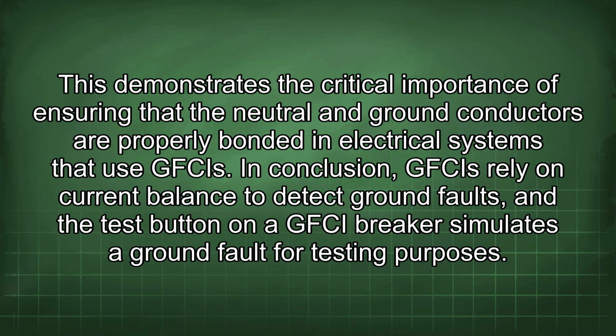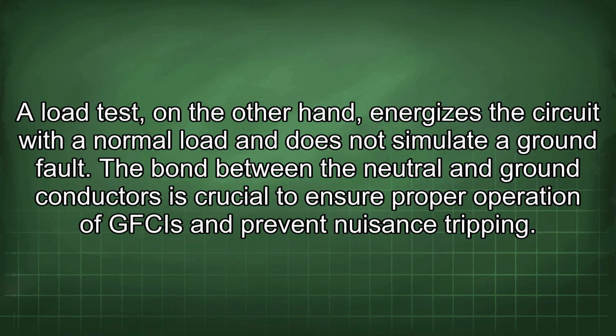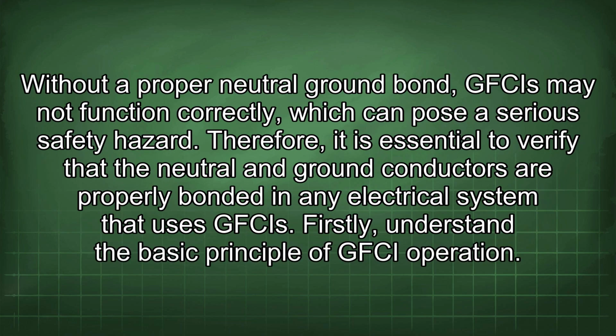In conclusion, GFCIs rely on current balance to detect ground faults, and the test button on a GFCI breaker simulates a ground fault for testing purposes. A load test, on the other hand, energizes the circuit with a normal load and does not simulate a ground fault. The bond between the neutral and ground conductors is crucial to ensure proper operation of GFCIs and prevent nuisance tripping. Without a proper neutral-ground bond, GFCIs may not function correctly, which can pose a serious safety hazard. Therefore, it is essential to verify that the neutral and ground conductors are properly bonded in any electrical system that uses GFCIs.